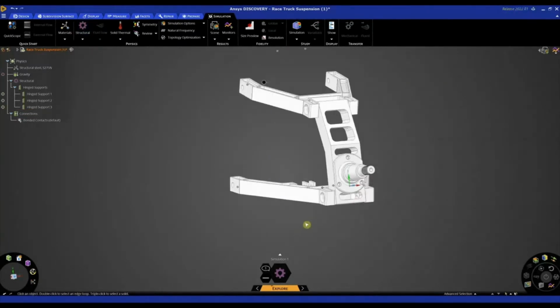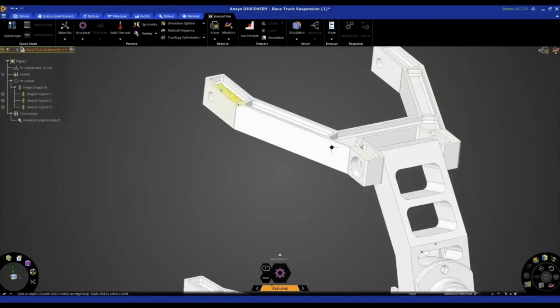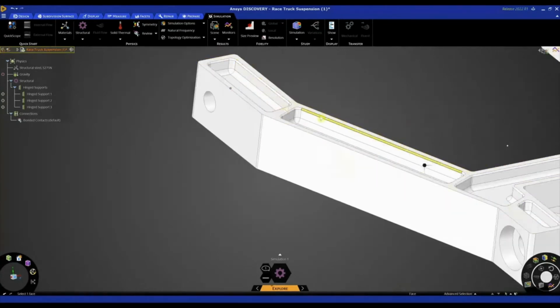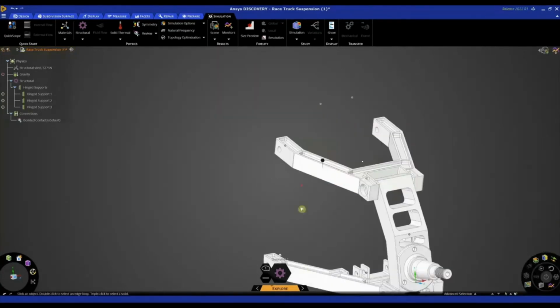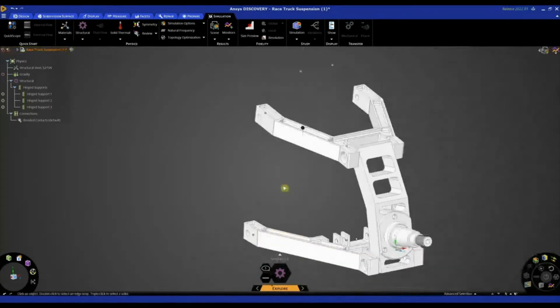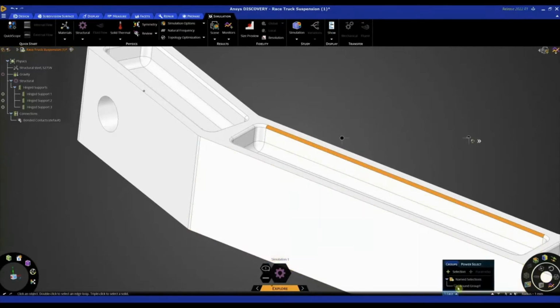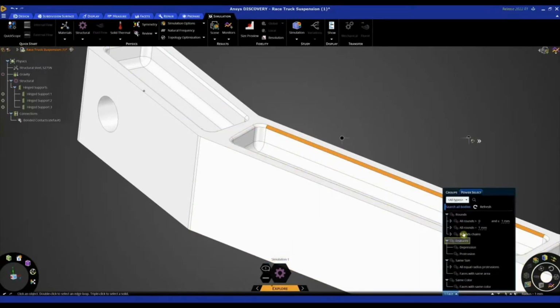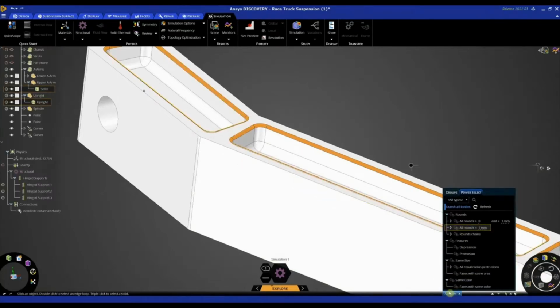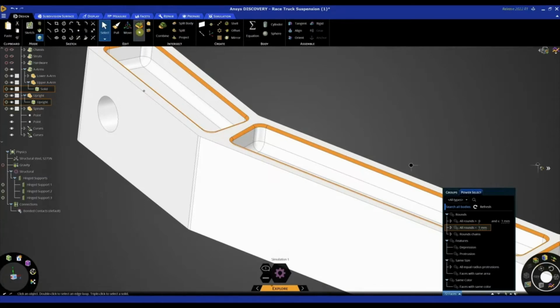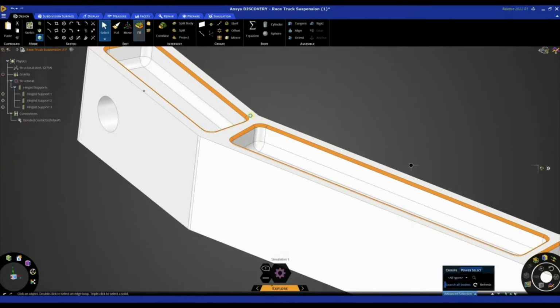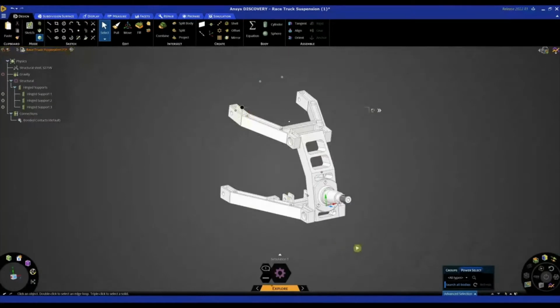The next thing to do, before I go on to add a force somewhere, is a bit of defeaturing. Looking at the model, there are still some little 1mm rads along this edge, and if I look at the bottom side, they're no longer there. So let's use our power select tool to quickly defeature those. If I click on the face and use my power select tool down here, I can select all the rounds equal to 1mm. You'll notice that's picked up 72 faces. We can go into our design tab and hit the fill tool. We can see those instantly get removed.